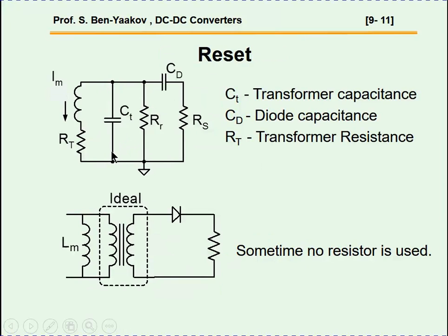So the circuit we have here during the off time is the current going through this parasitic capacitance. There's another diode here. This is the diode being reverse biased. And this actually has a waveform, and the current will have a sinusoidal waveform, and this will be the voltage here. Now the voltage here may be high, and this is something to worry about because this diode is reverse biased, and if this voltage, which is negative, is just getting too high, it might damage the diode. So this is something to worry about. I'll talk about it next.